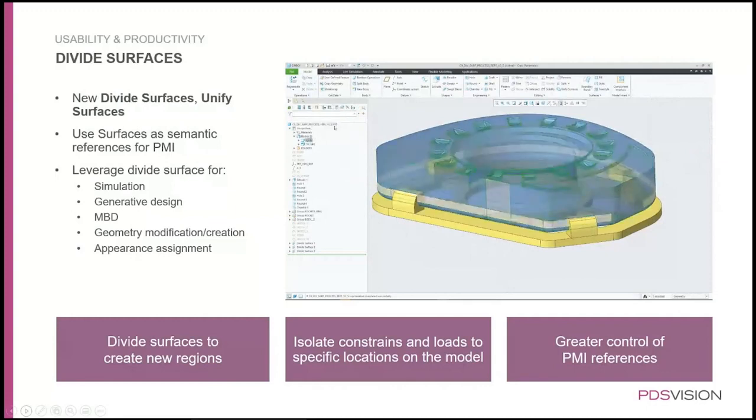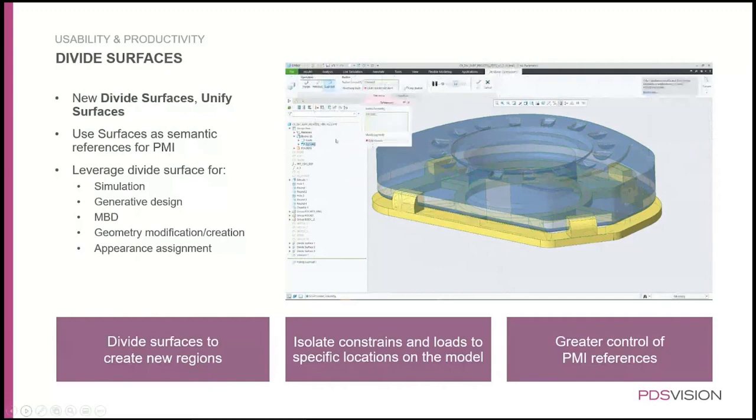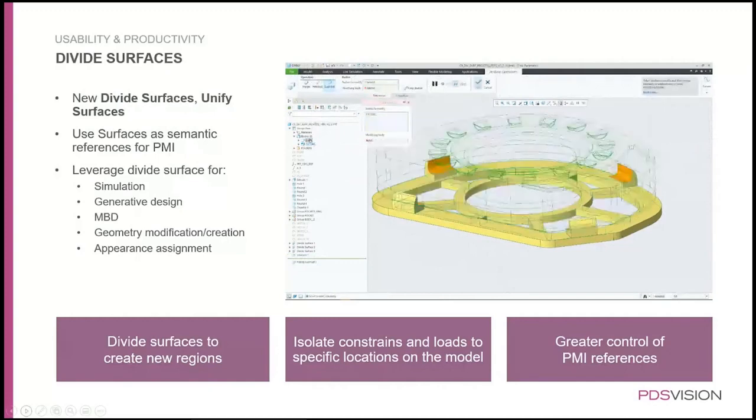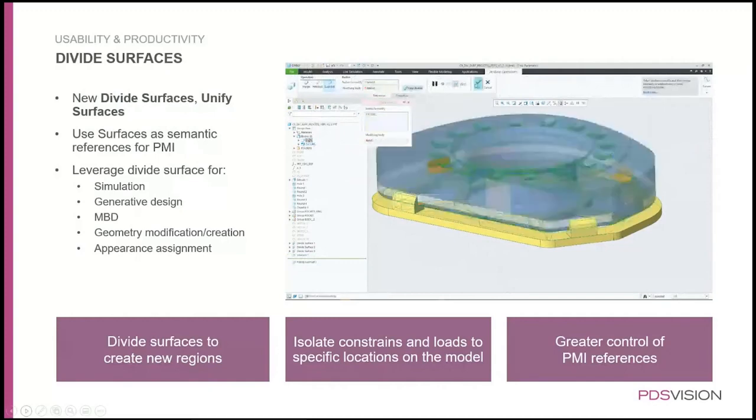And then we are using something in here. As you can see, the yellow geometry penetrates the blue one. What we do is insert curve, which highlights the intersection volume between those two, then make a cutout so that you just subtract the jig away.